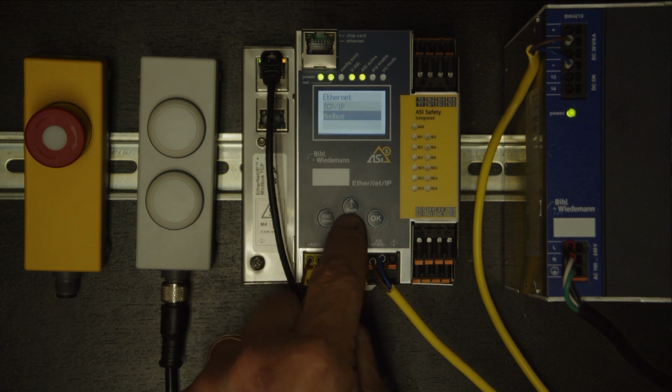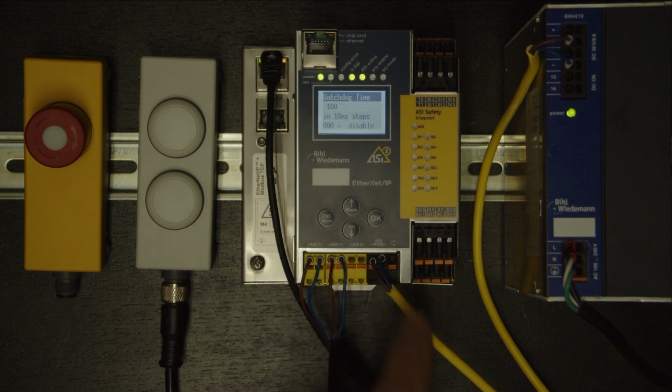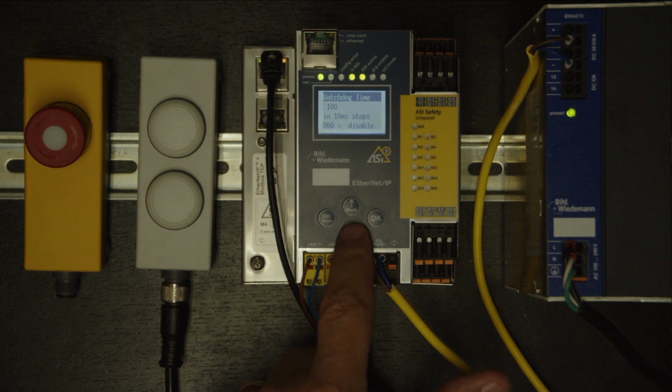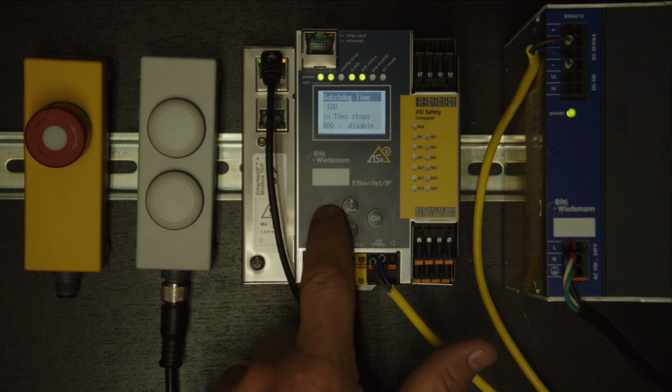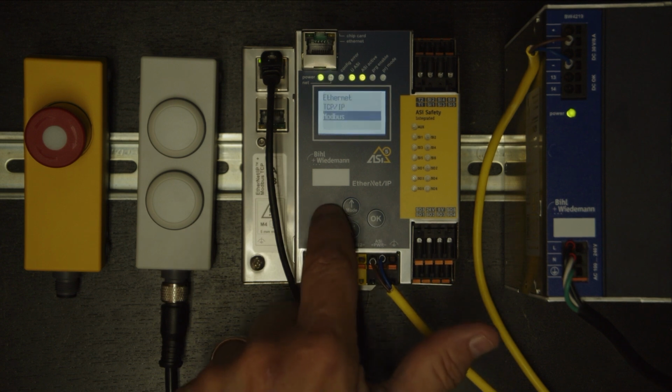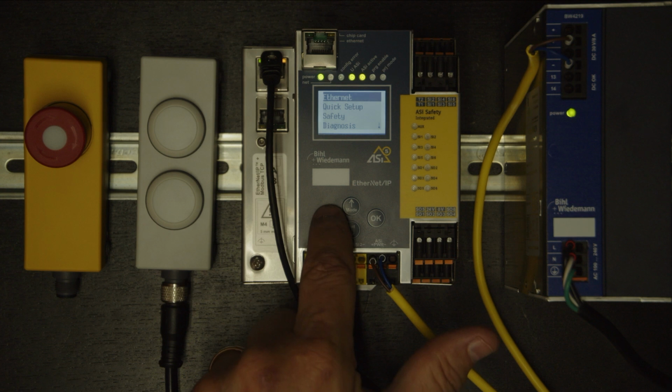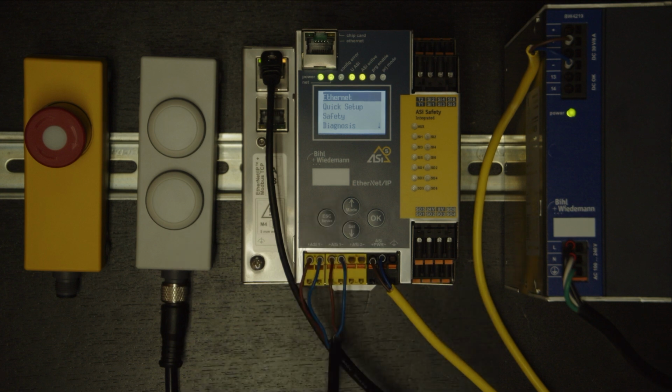The only thing left is any Modbus parameters. The only thing there to be configured is watchdog time. This is how many 10 millisecond steps I will wait before I decide that the Modbus TCP client, in this case an OCS all-in-one controller from Horner Automation, is taking too long to talk to me, and put the network into a safe state. That's what that's all about. The default is 100 steps of 10 milliseconds, or 1 second. I'm happy with that, so I'll just back out here. So I'm fully done with my Ethernet configuration.